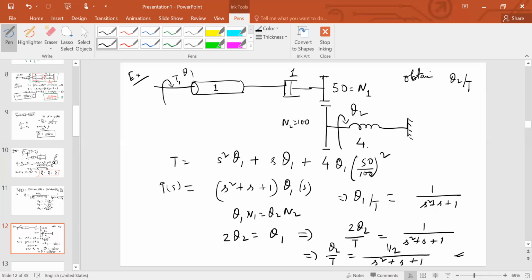So we shall solve the armature control problem in its entirety and show you how to obtain the transfer function of the applied armature voltage, that is the input, to the speed or the position of the shaft of the motor. And we shall leave as an exercise for you to derive a similar transfer function for field control. Down the line we shall see how these two modes differ.